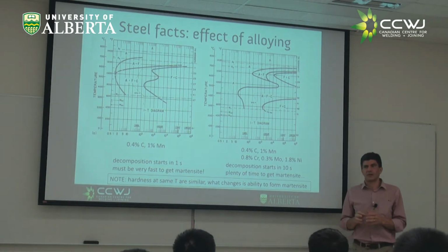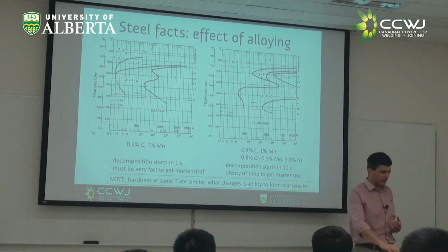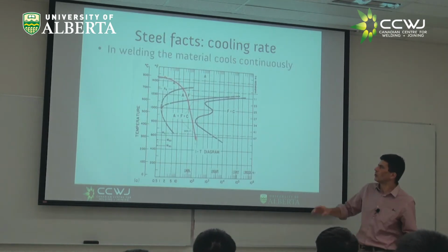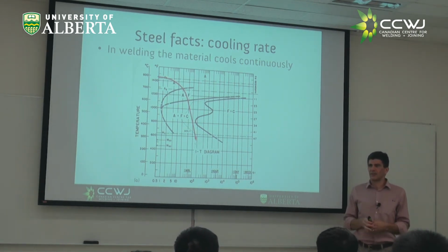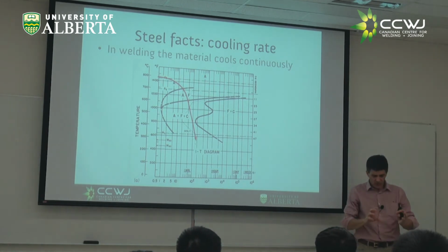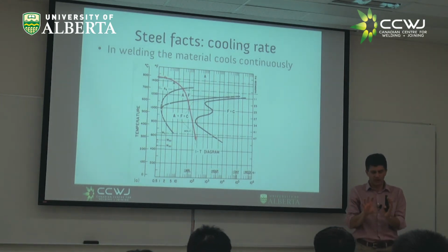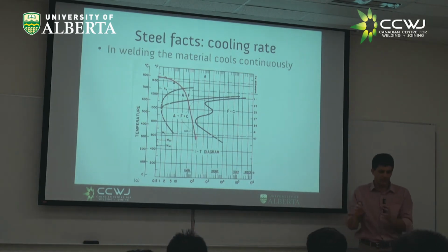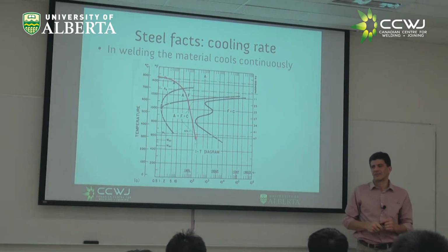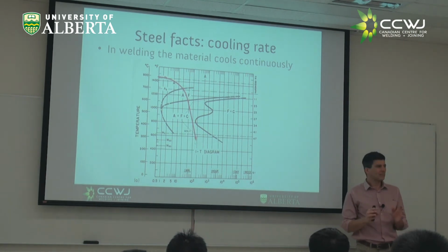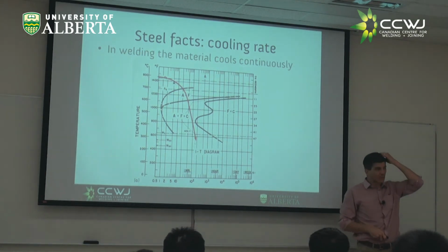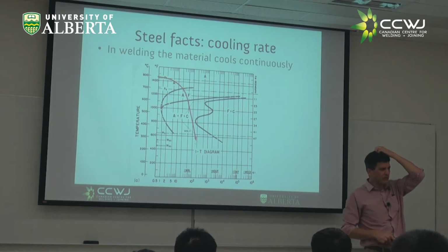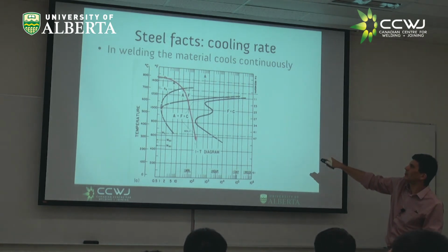But what is good for welding? Well, in welding, we have a constant cooling rate, right? Constant cooling. But the experiments I was telling you didn't account for cooling. They said you hold in austenite, then you quench in a salt bath and you hold it at 600 or at 450. Nobody does that. But it gave me a way of explaining things to you that seem relatively easy. If it didn't seem easy, it could be so much more complex. The reality of welding, and the way metallurgy is starting to do things, is this continuous cooling.